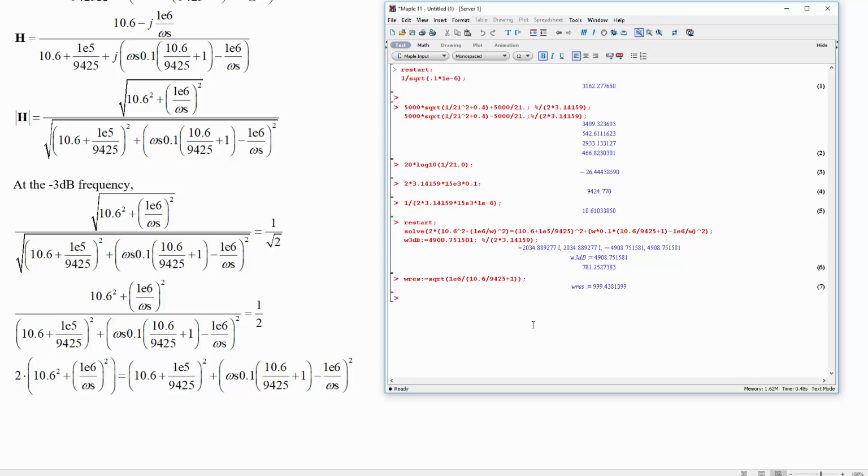And if we take this and divide by 2 times 3.14159, then we end up with 159 hertz for that. Oh, you know, I forgot a 0.1 in there. That makes more sense. So it wasn't just this 10.6, it's this thing, but then we've got a 0.1 for that. Okay, all right, yeah, that's more like it. So 503. So 503 is our resonance.